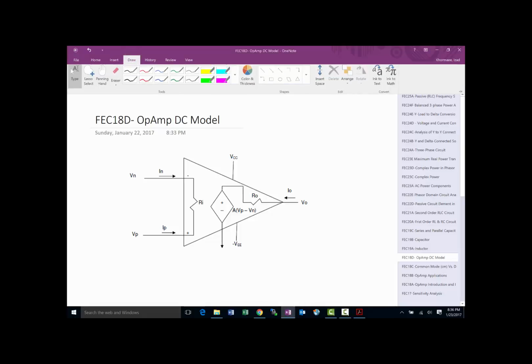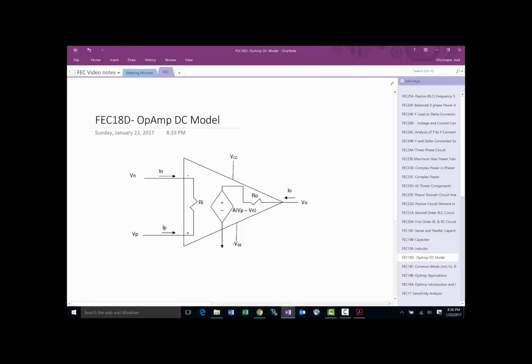So in this case, you basically give up all the ideal OpAmp, forget about all the conditions that came from there, and what happens in a circuit, you literally replace your OpAmp with this diagram. So in other words, from Vin coming in, you're going to put an Ri.